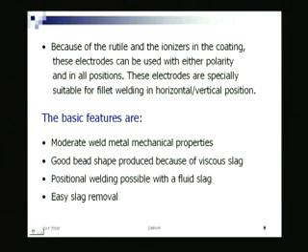Here it can be used with either polarity, which means I can even use an AC source. For general purpose welding you can use that, but definitely for shipbuilding or where you want superior weld properties, you have to look at whether this gives you the required mechanical properties or not. These electrodes are specially suitable for fillet welding in horizontal and vertical positions.